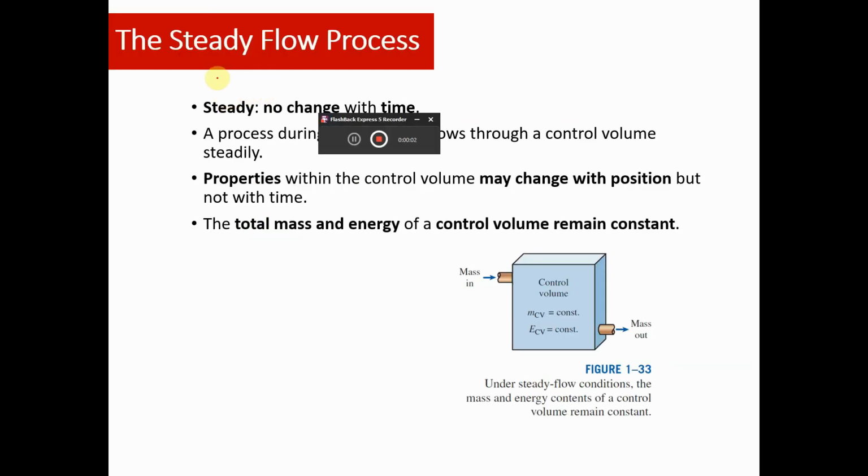Another very popular term that we always use for any situation related to thermodynamics, mass and energy balance is the steady flow process. By definition, steady means no change with time. So it is a process during which a fluid flows through a control volume steadily. A control volume is an open system, and in industry most equipment can be treated as an open system where we assume a steady flow process.